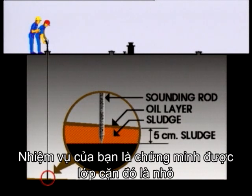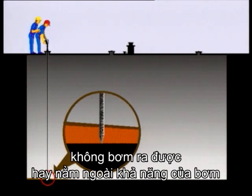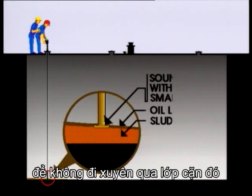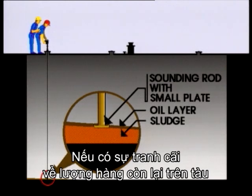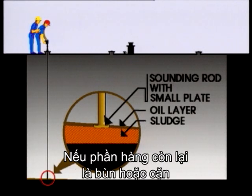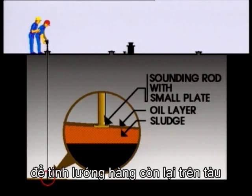Your job is to prove that the findings are negligible, unpumpable, or out of reach of the vessel's pumps. It's a good idea to use a rod with a flat end to avoid penetrating the sediment. In this vessel there are only vapour control valves in the aft end of the tanks. If there is a discussion about ROB, and the dip clearly indicates liquid, use the wedge formula or wedge table to calculate remaining cargo. If the dip indicates sludge or sediment, you should also suggest using the wedge formula to compute ROB.